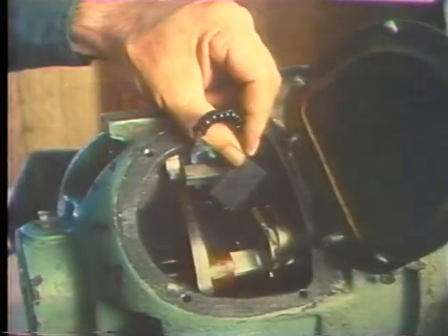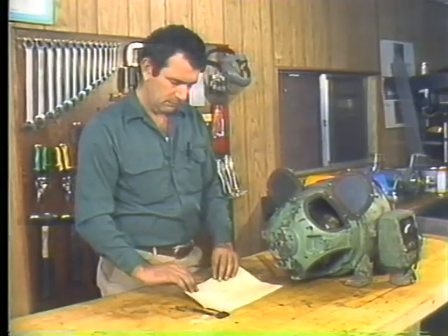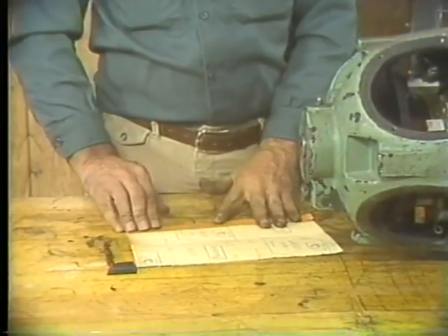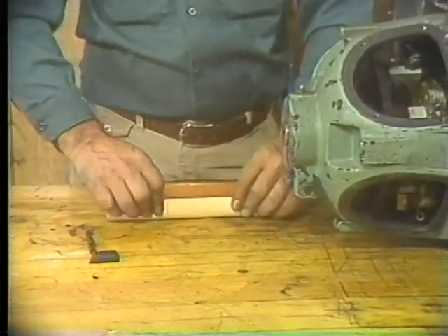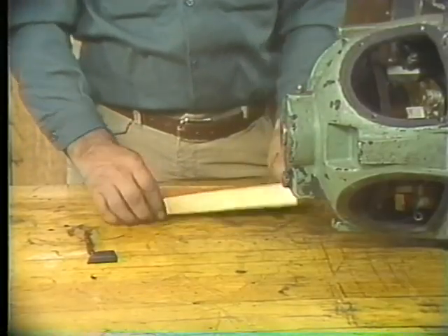When you're sure the rigging's in place just right, you can reinstall the brushes. If a brush needs to be replaced, make sure the one you put in is the right type and grade for the motor. Now, in some plants, all new brushes must be seated. Follow your plant's procedure if there is one. You can seat a brush a number of ways. Since this is a small motor, we're going to use some extra fine flint paper to do it. If you decide to use this method, bear one thing in mind. Don't try to substitute emery cloth or emery paper for flint paper on a DC motor.